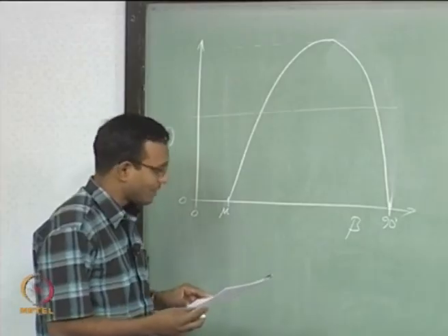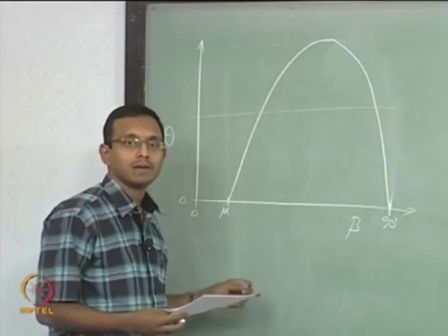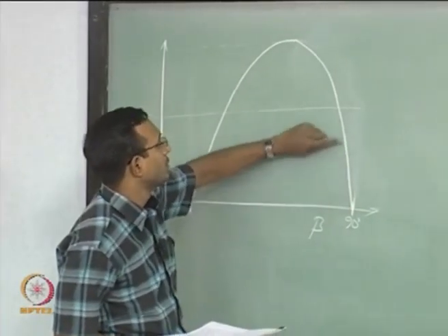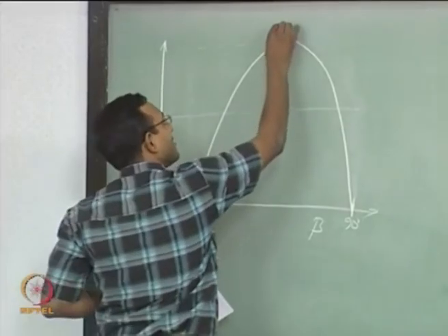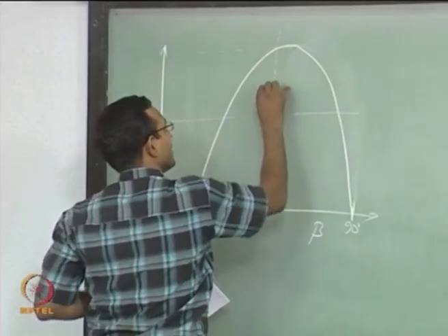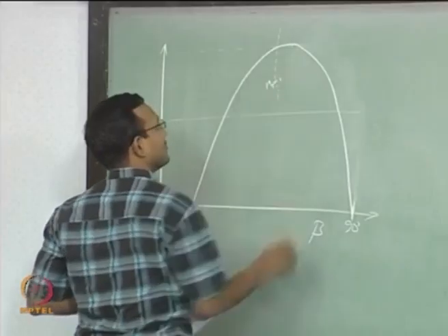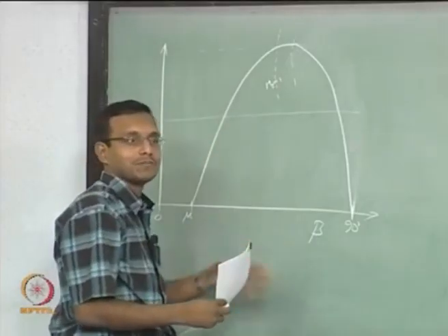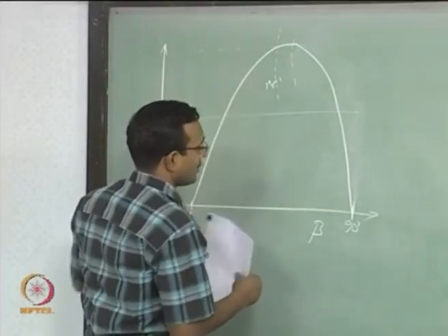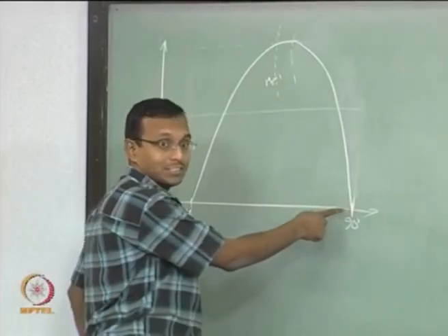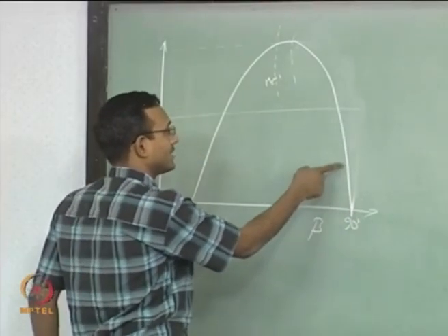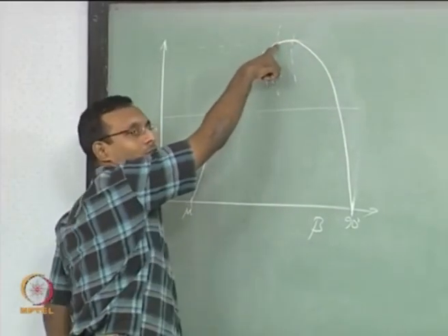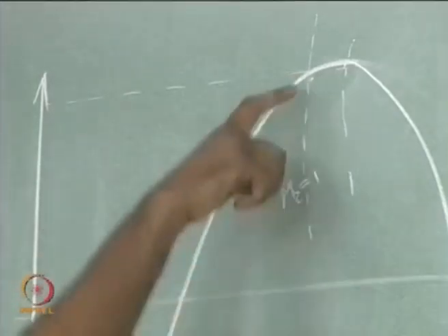Okay. If I look at M2, the Mach number behind the shock, it starts with subsonic. We already had this dotted line we drew last time, it was going like this, we said this is M2 equal to 1 line, and we said this is our theta max line, we had two curves like this going across different Mach number lines. So, if I think about it, it starts with very low subsonic, this is the strongest shock, very low subsonic, and is going slightly higher and higher Mach number, and then up to here it is becoming M equal to 1 at this point, that particular beta value it will be M equal to 1.